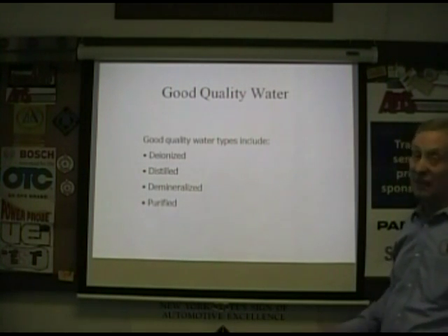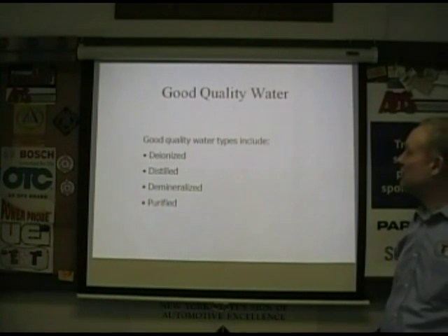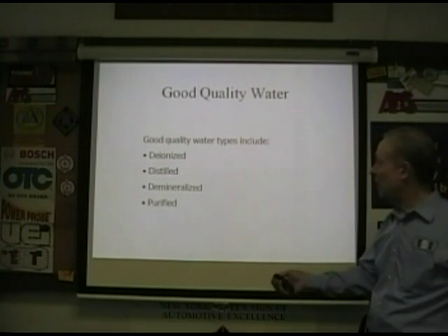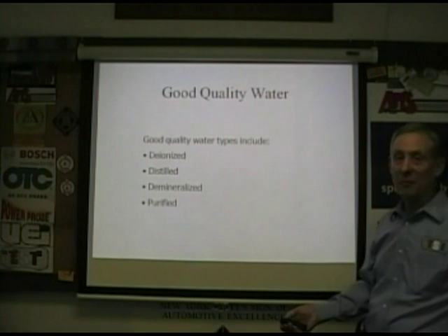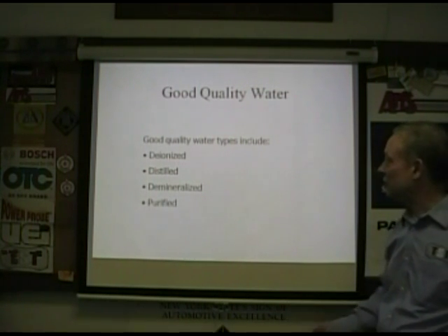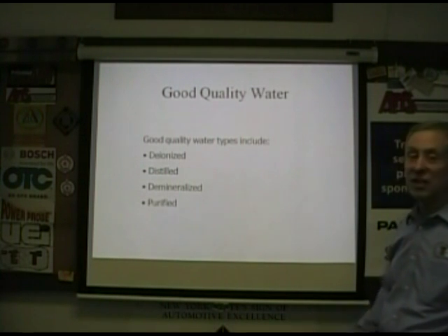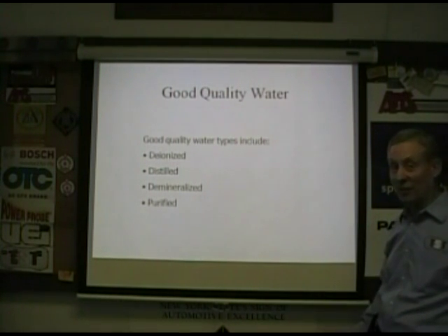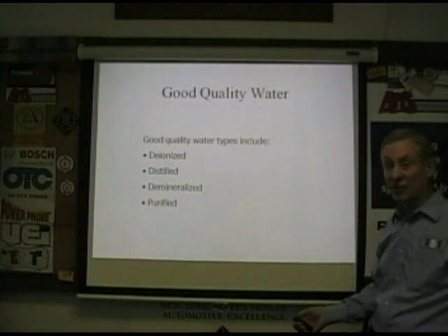The slide says, use deionized, distilled, demineralized, or purified. For me, I like distilled. In my mind, there's nothing cleaner than distilled. A lot of manufacturers will tell you that you need deionized. The bottom line is it has to be clean. If in doubt, if you have stains on your sink at your shop, and they look like iron or anything else, you probably have an issue with your water.